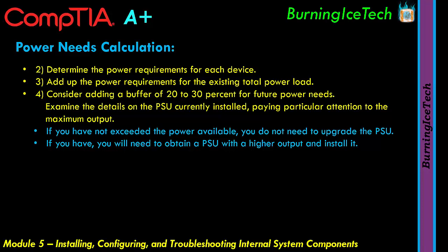Consider adding a buffer of 20 to 50% for future power needs. Yes, that applies to anything in life. Whether you're building a PC, building a network, building a server, you always want to add a little buffer for future growth. So if my power consumption is, let's say 100, I'm making up a random number. Let's say it's 100 watts. Impossibly not going to be 100 watts, but let's say it's 100 watts. You want to plan for 120, 140 watts, somewhere in that vicinity, so that if you need to add something in the future, you don't have to replace the whole power supply again. That's just going to cost you more money in the long haul. You generally want to try and avoid that.